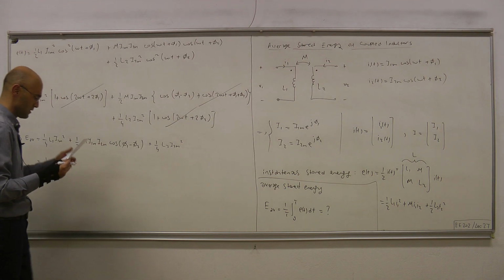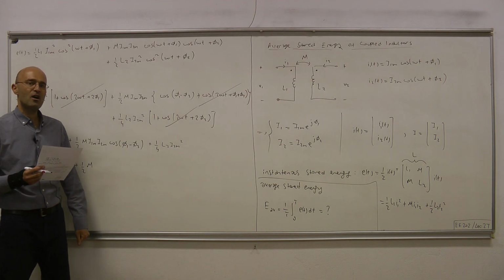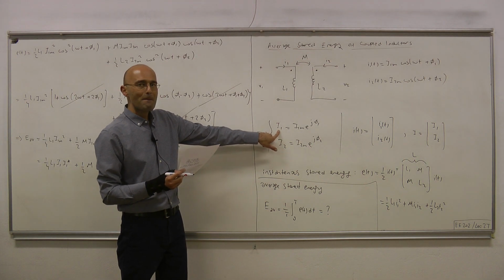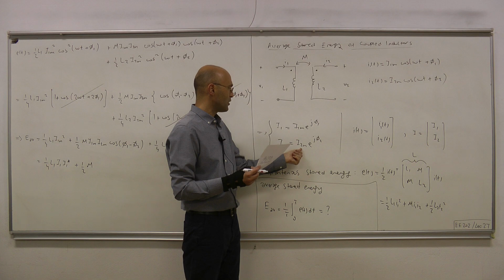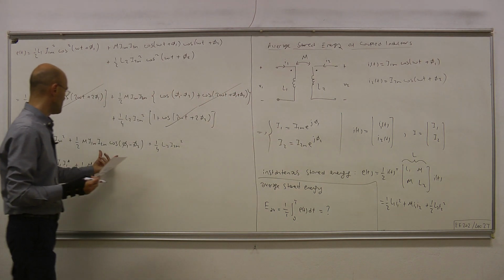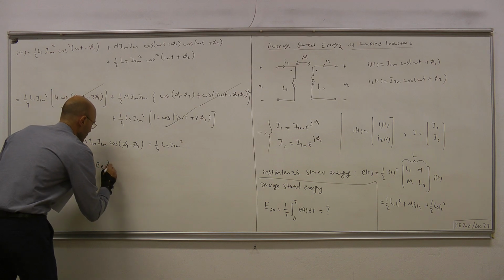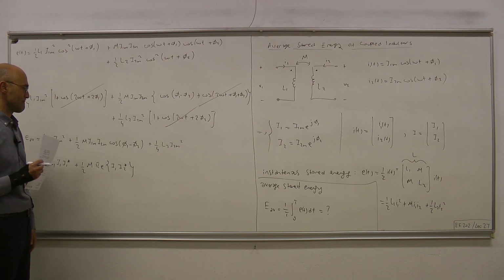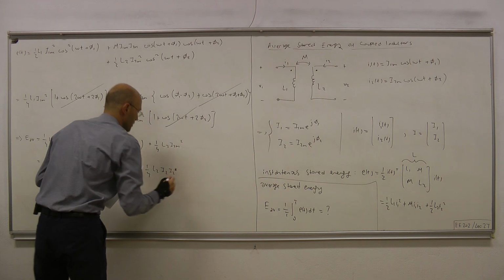I1 conjugate. Then we have 1/2 times m. Now here we have I1 magnitude, I2 magnitude times cosine of the difference. It's not difficult to see that this equals I1 times the conjugate of I2. You obtain the complex number with magnitude the product of the magnitudes, and the phase the difference, due to the conjugation of the second term. This then produces the real part of that complex number. In other words, this can be written as the real part of I1 I2 conjugate. And we have 1/4 L2 I2 I2 conjugate.